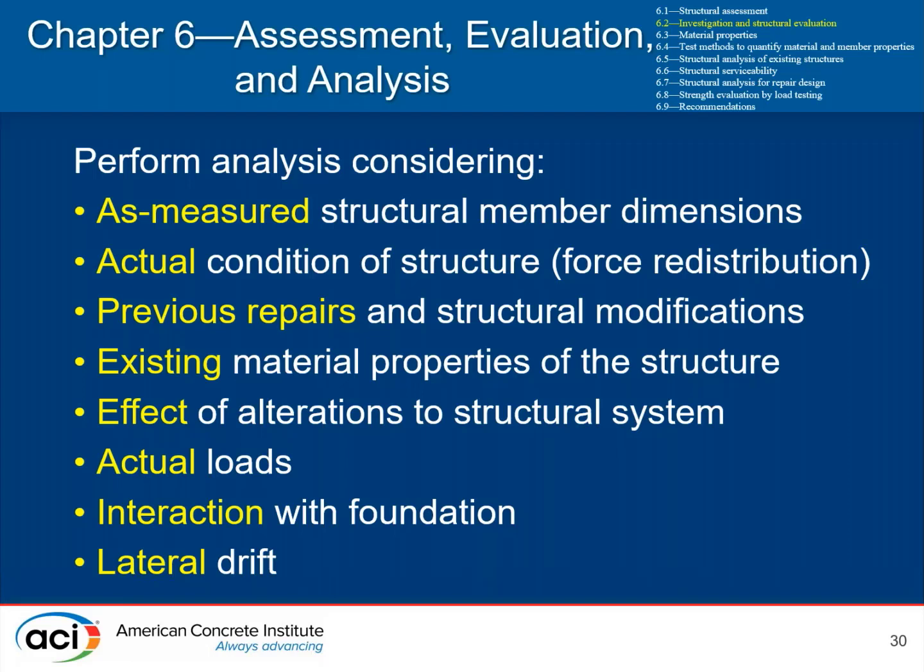Previous additions, for instance: do things look like they were done with purpose? And are there any indicators that things that weren't in accordance with the original design or confirmed conditions are present? So previous repairs and structural modifications need to be addressed and evaluated. We sometimes see that previous repairs, particularly those that have not followed industry standards, are failed or cracked or potentially not performing in the manner that the person that conducted the repairs had intended.